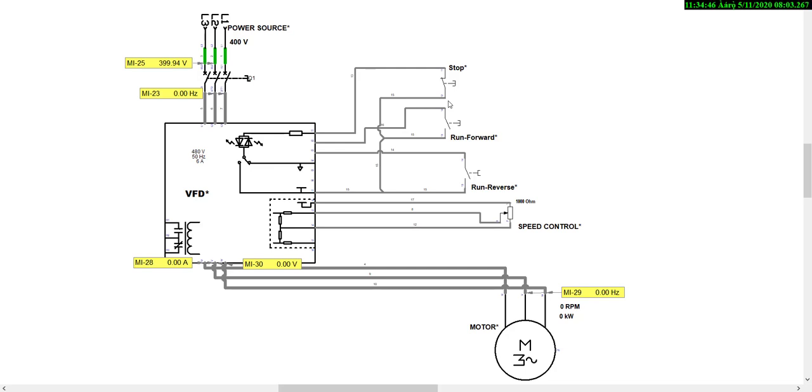That means it will allow our motors to start from 0 to the maximum RPM gradually, preventing a very huge surge of current, which we know as starting current. So VFD also helps to regulate that. In this system, we have our power supply, and we have our power out, and we have our motor control. So we'll start this system by activating our contactor, our circuit breaker.